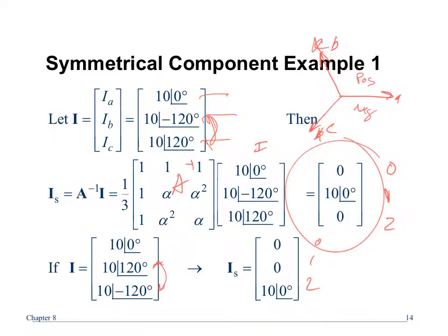If we did zero sequence, what would you measure? That's a much harder one, isn't it? Because you can have an unbalanced set of phasors and you can have no zero sequence current. Right? We already talked about having positive and negative could be enough. The zero sequence element is determined by the ground. So I actually need additional information. I need to know what the ground is. We'll get to that.